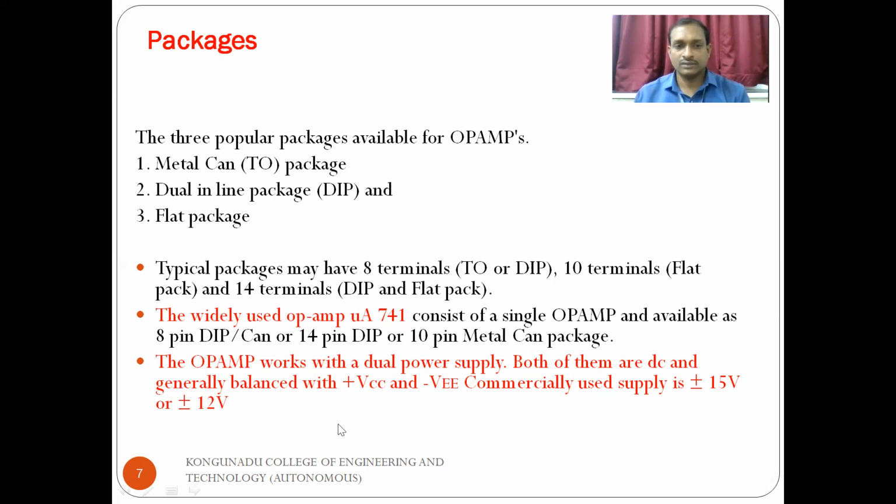Here we are going to provide the dual power supply connections for plus VCC and minus VEE. Commercially we use plus or minus 15 volt or plus or minus 12 volt for applying the supply, that is VCC and minus VEE.